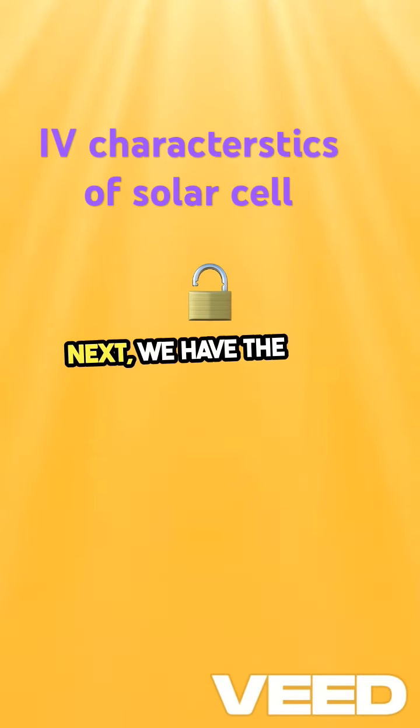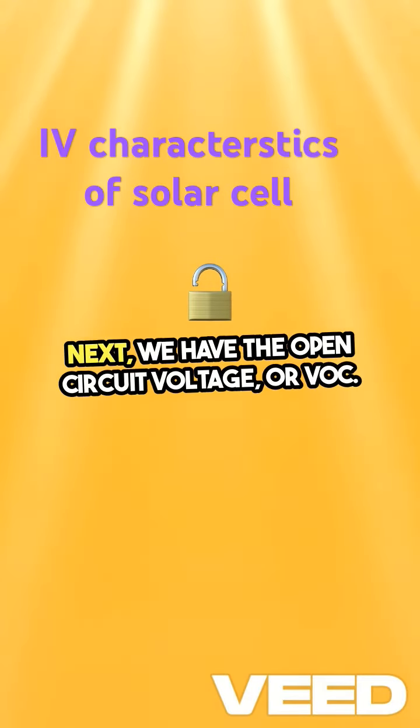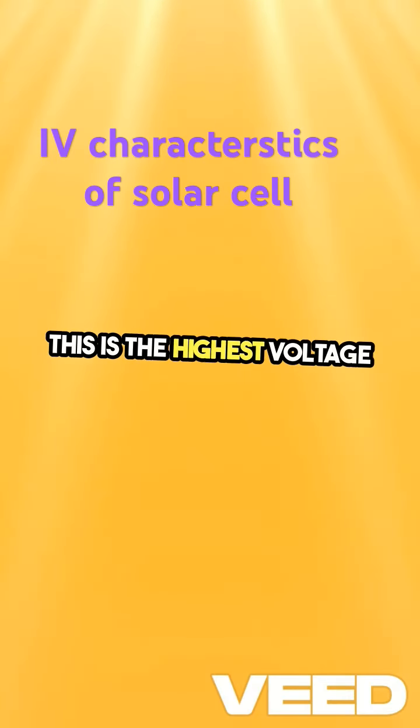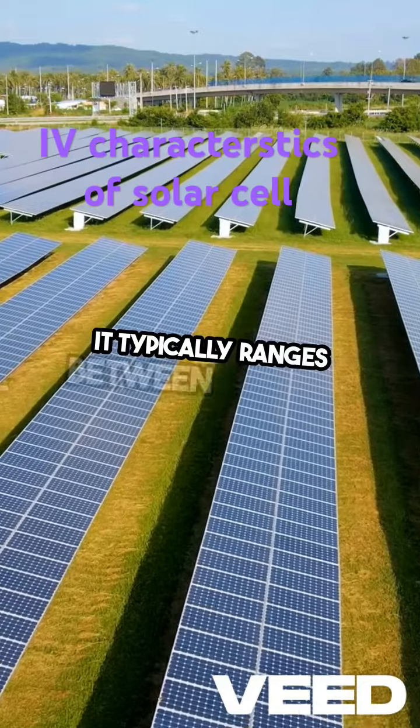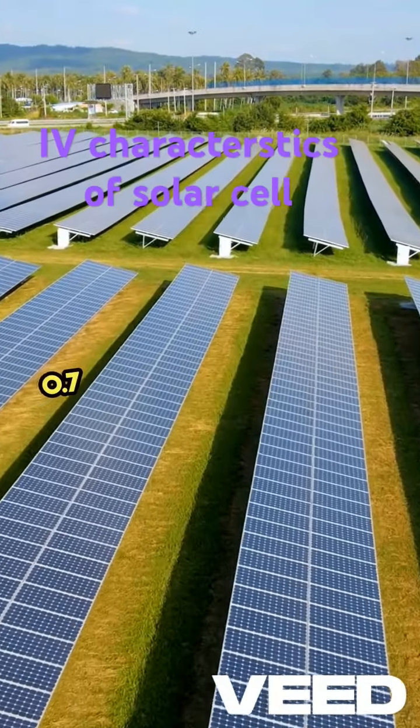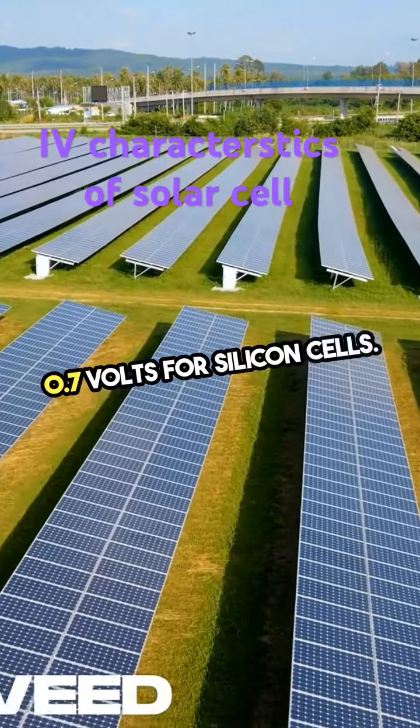Next, we have the open circuit voltage, or VOC. This is the highest voltage the cell can produce when no current is drawn. It typically ranges between 0.5 and 0.7 volts for silicon cells.